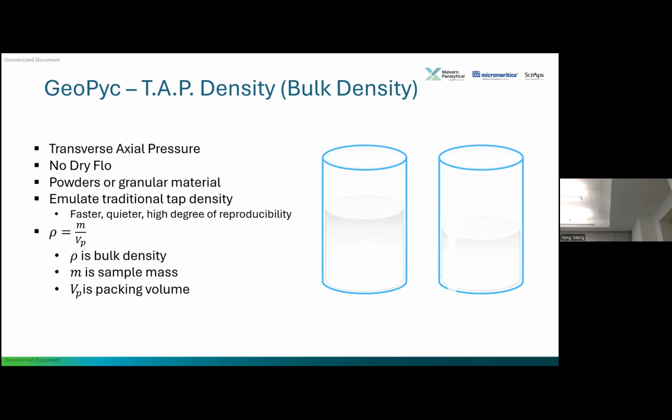The tap density calculation, this is if you're putting a powder in there. So what it'll do is, you'll tell the instrument what force you want to apply. It'll keep applying different forces and look at volume changes and record those volume changes. So the blank will be just no sample at all, so it knows where zero is. Then it'll just keep applying forces when you have the sample introduced. And you can see what consolidation force can be applied and what volume you actually get from it.